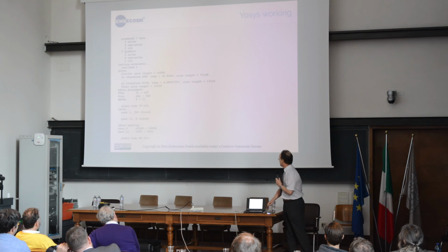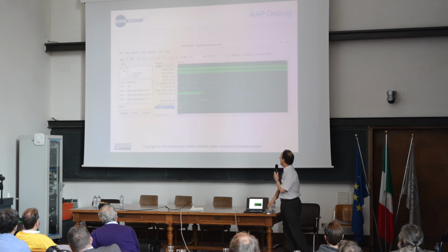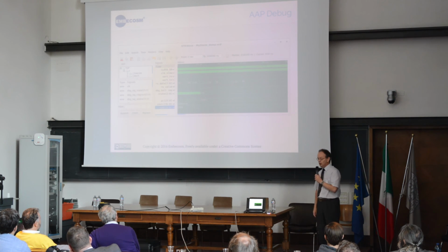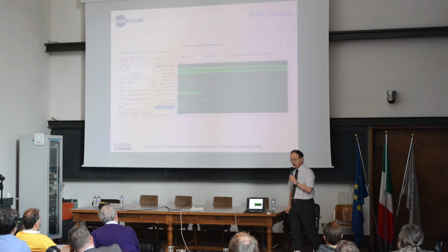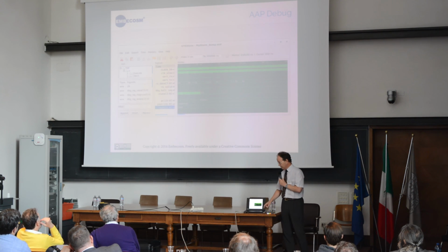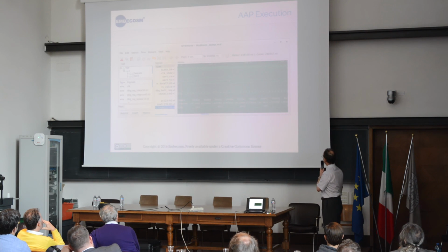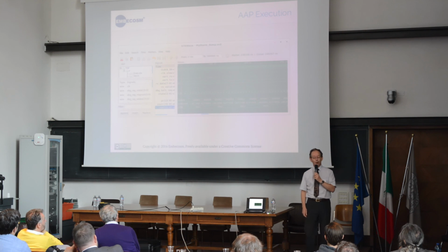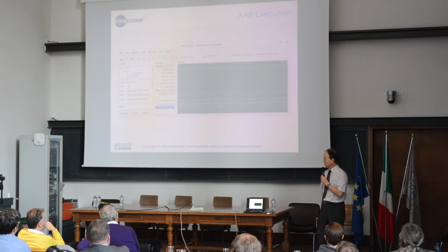But just to prove it, there's Yosys running and giving me some nice output. There is the AAP starting up. We use the UART for debug, just for easy tutorial migration. We teach you how to implement a UART, then you can use it. And we have a little simple character-based protocol for controlling the processor. And there, if you can see at the bottom I'm showing R0, and you can see it's going 1, 2, 3, 4. It is actually counting up, and my program's executing correctly.